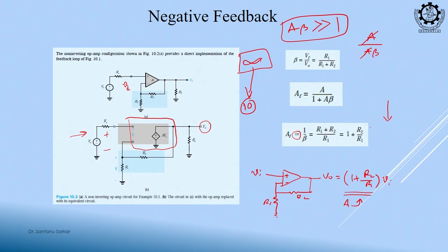And how is this coming? This is the voltage that we are subtracting from this voltage. So, what is this voltage? This voltage is Vs. So, what is this node voltage? This will also be Vs, since no current flows. Input impedance of the op amp is infinite. So, I is equal to 0. So, if no current flows, whatever Vs is here, that will come over here.